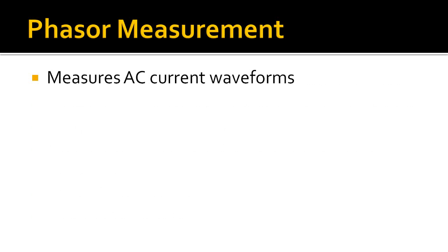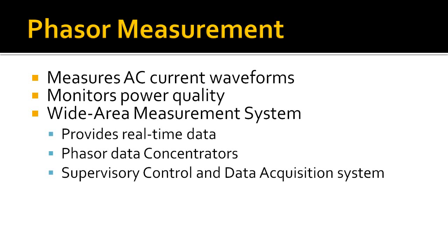Smart grid utilizes high-speed sensors called phasor measurement units to monitor power quality. Ideally, the waveforms of alternating current should be identical throughout the entire grid. Phasor measurement units are integrated all through the system, allowing data to be extracted regarding a particular position's waveform dimensions along the grid. Networks with this level of unit installation make up a wide area measurement system and can provide real-time data.